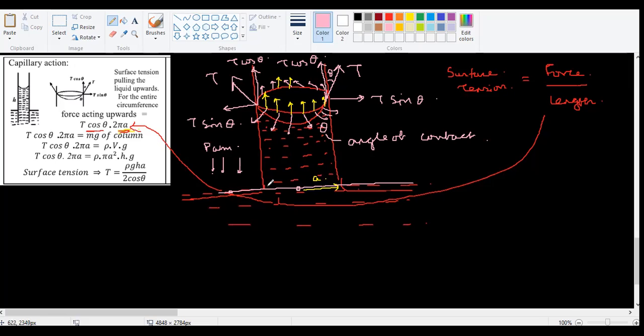Whereas here, this is P atmosphere. Whereas here, who is acting on top of this? It's the P atmosphere plus this liquid weight. So this liquid weight is also acting on this part. What I can say is maybe I have not given the steps here properly. If I take this X and Y location, pressure at X should be equal to pressure at Y.